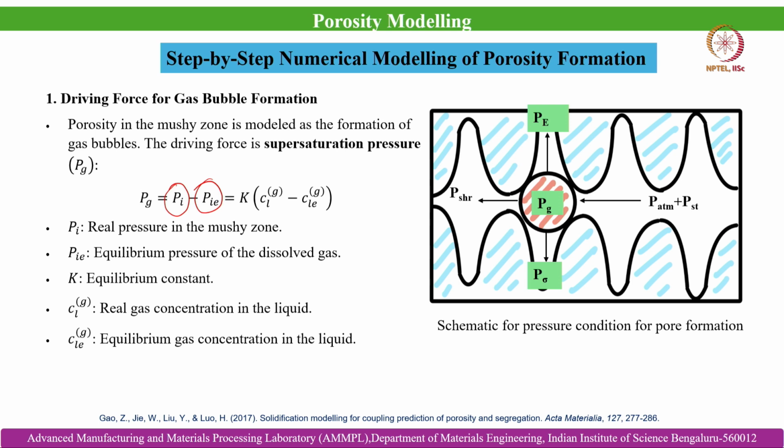Pg. There are several other forces which assist, and some forces which try to compress or negate the pore formation within the solidifying mush. What are those? We will learn in the subsequent slides. You can also see over here the force due to the shrinkage of the solidifying mush, the force due to the atmospheric pressure and the metallostatic head present within the solidifying liquid melt, the force due to surface tension, and the force due to the thermal contraction of the dendritic mush which is solidifying.